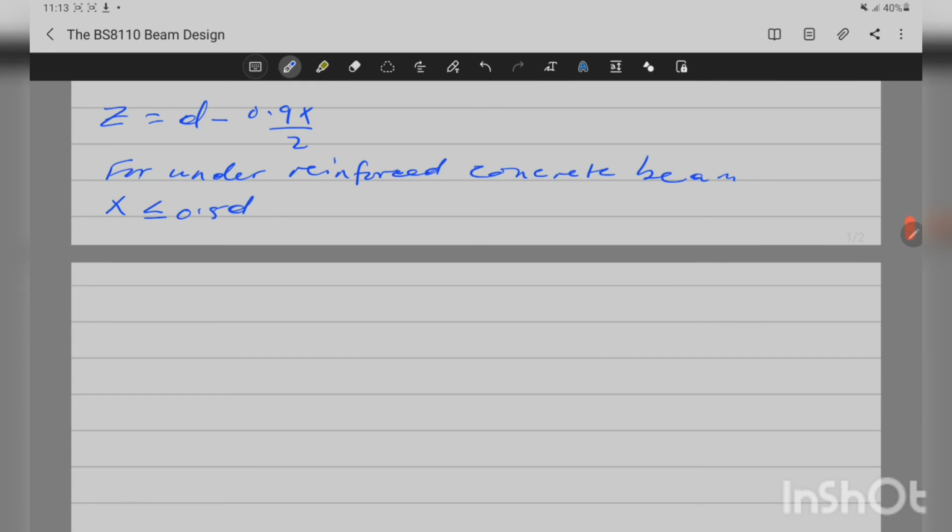Now let's substitute the values. Also, the material factor of safety for concrete is 1.5, and for steel is 1.15. But for now, we are going to get the maximum moment using the equation for the concrete section, because we can specify the size, the geometry of the section, and then determine how much reinforcement goes into it. So it is easier to go with the concrete section.